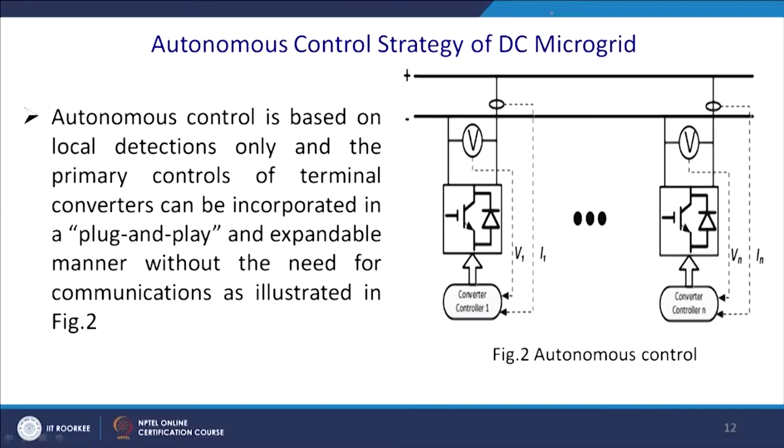Similarly, in the evening when solar goes out, ultimately you have to depend on the grid, and the grid is also at its peak price. So, the battery storage may be the slack terminal, and at night maybe when your grid is cheap, then your active rectifier will be the slack terminal, and the others will be follower power terminals. So, accordingly it will change.